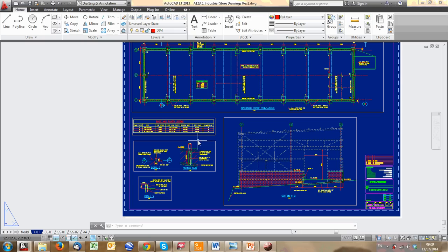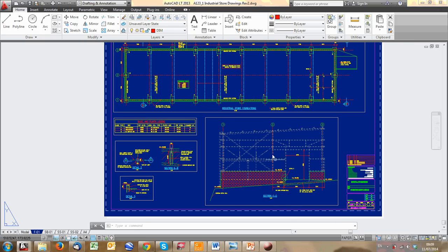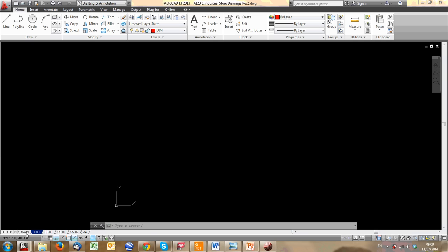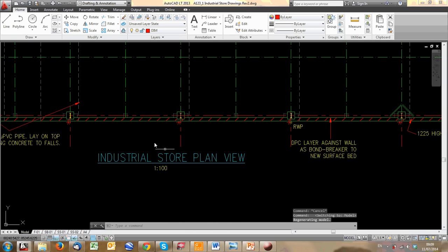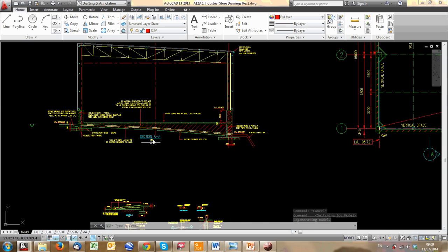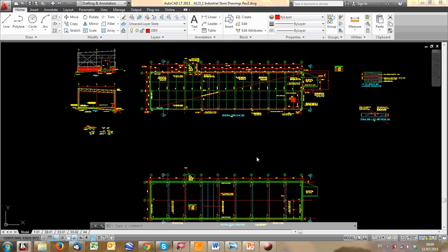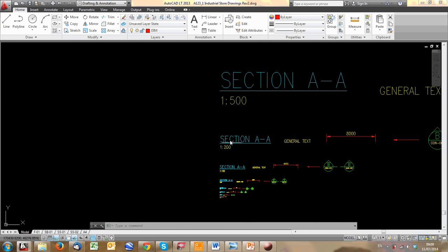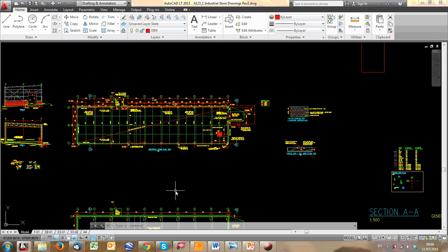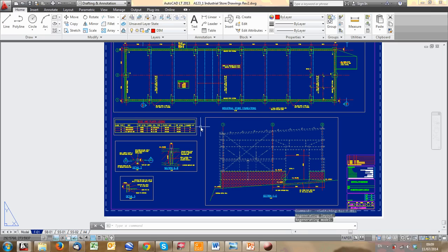But if you look at the text, the text is all the same size, although in model space you'll see the text for 1 in 100 much bigger than a 1 in 50, which is bigger than a 25. And those are standards, which we'll get to just now, that you can use to set it up such that whatever scale you have, they all match each other, and it produces a drawing that is clear, that is easy to understand, and it makes sense.